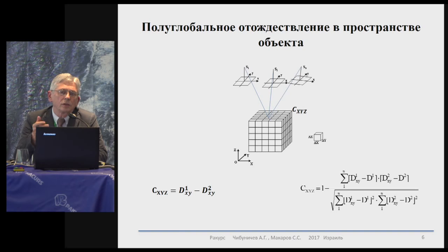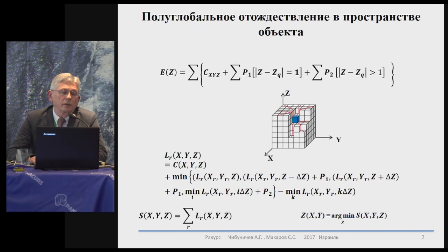As a criterion for evaluation of this matching, we can use not only differences but also the correlation coefficient, which naturally can increase the level of matching. The matching will be much greater, especially in the dead zones. Later on, we analyze not the matching, not the neighboring lateral parallaxes, but rather the heights of neighboring voxels. And based on the same principle, just like in the classical SGM method, we increase their value.